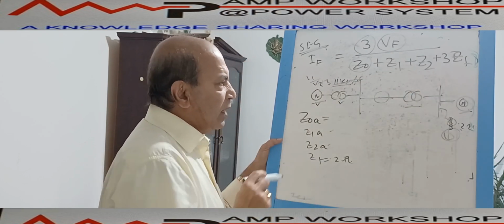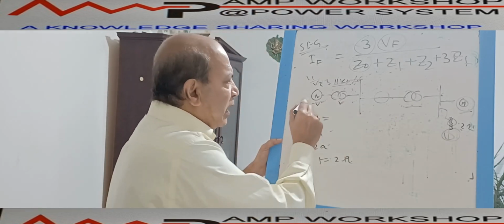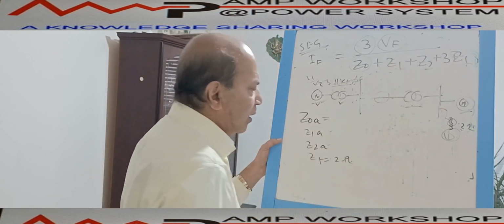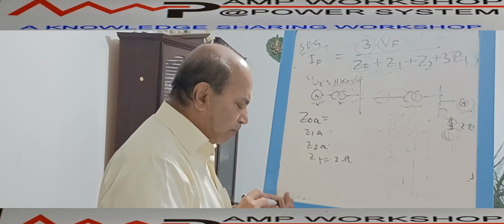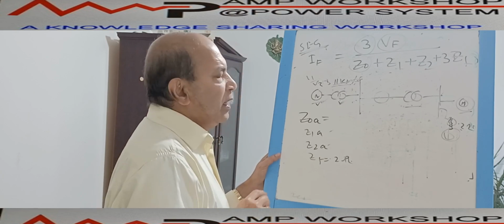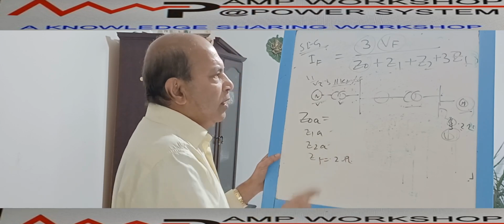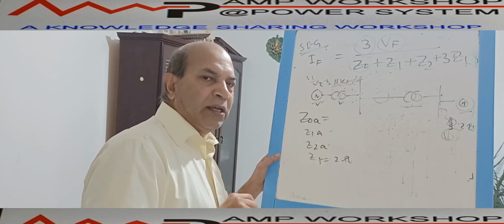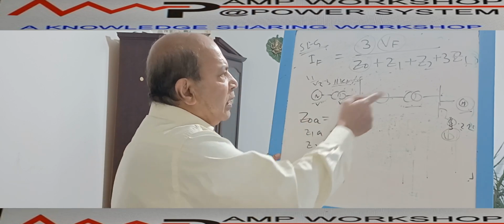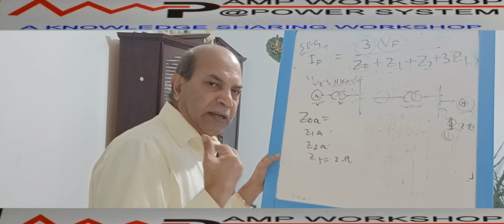So why did we say that the sequence impedance of individual loads is important to calculate the short circuit current? That is clear from this expression. Whatever demonstration we have given in slide number 59, video number 59, is very, very important to calculate the short circuit current for asymmetrical faults, because we have shown how to calculate the zero sequence, positive sequence, and negative sequence impedance for the various types of load that we discussed in the last part of video number 58 and the entire video of 59.